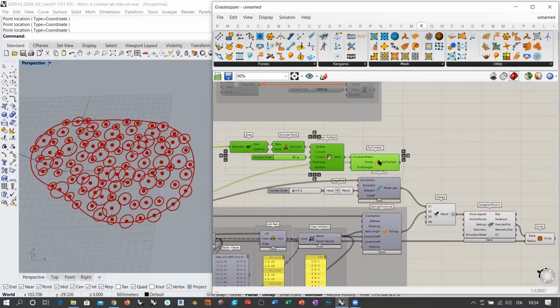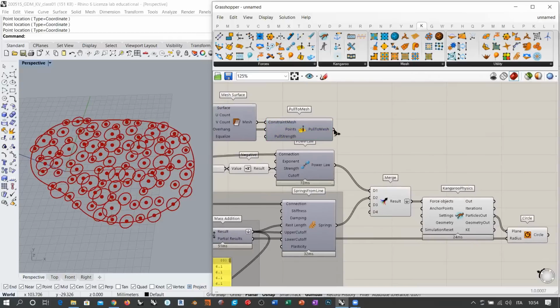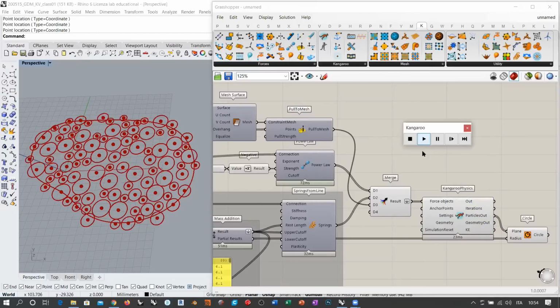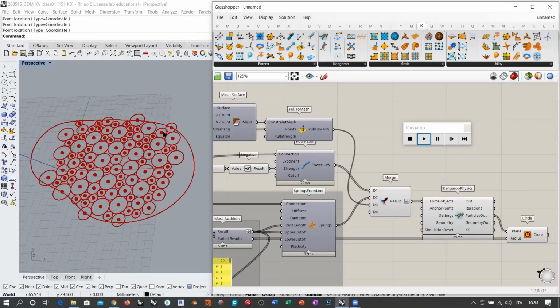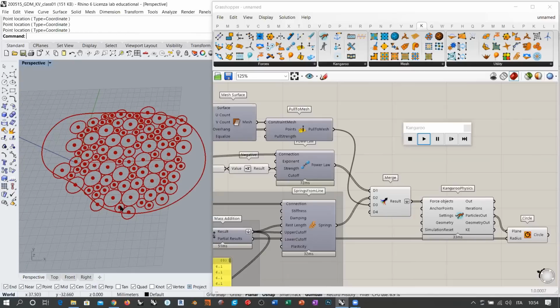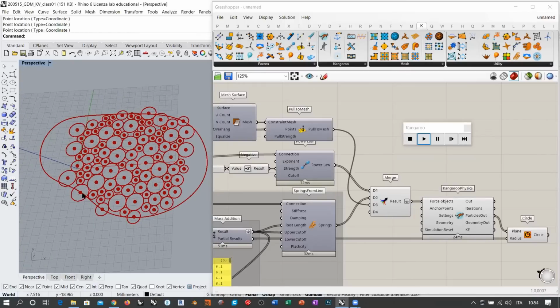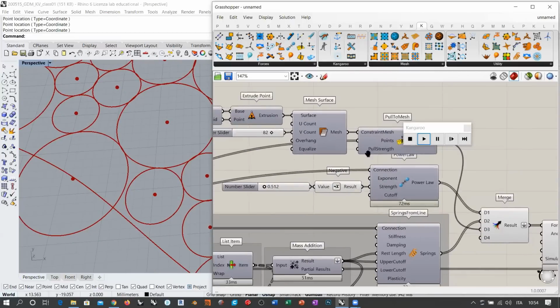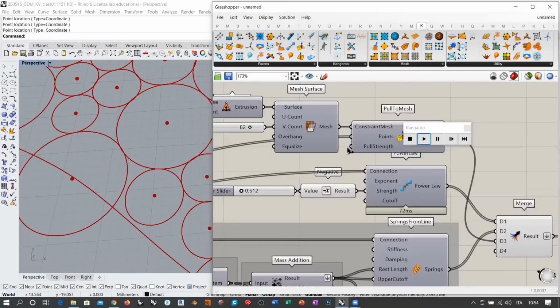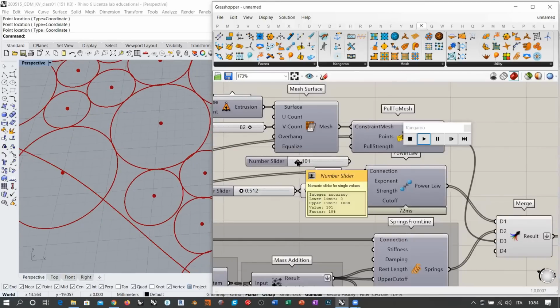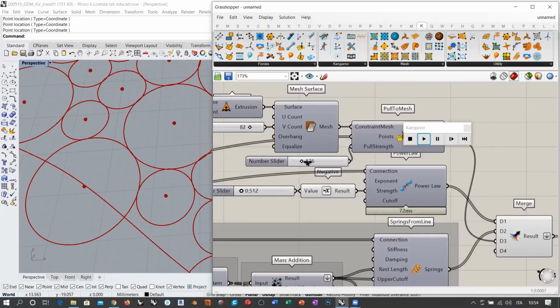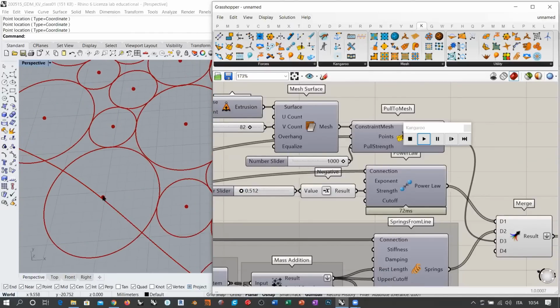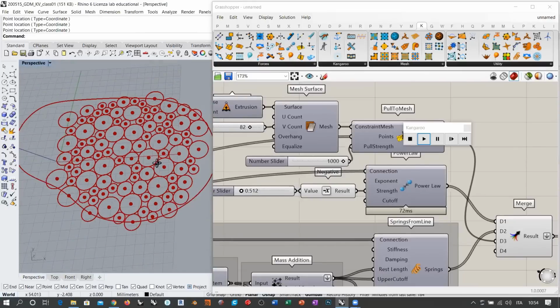So if I do this, let's check that it works. Let's reset the simulation, and let's run the simulation. Well, actually, the points are basically contained. You see that the points are inside, well, they might be going a little out. This is because of the pull strength. So if you want this to be more effective, you get a one-on-one slider here and eventually increase this. And you see that now the points tend to stay on the inside of your region, okay?